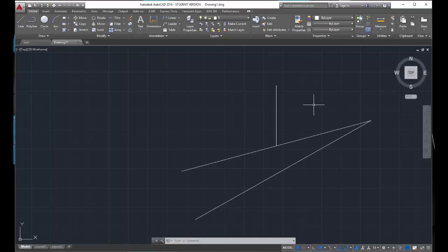All right, so that is object snaps, or O snaps. Now there may be times when you need to turn object snap off, and you can only really understand that when you start drawing objects, but 9 times out of 10 you are going to want to have O snaps on, so make sure that it's blue and highlighted and ready to go. Now directly to the left of the Object Snaps button is a symbol that looks like an angle. I affectionately call this the alligator beak. This is the Object Snap tracking button, and it's a kind of cool button.